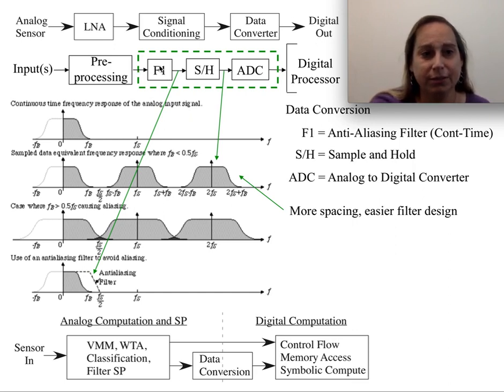And so usually that results in some sort of filtering stage. Then we do a sample and hold, which samples things, and then there's usually an ADC in the block. Typically when we talk about a data converter, you usually put the sample and hold in the data converter. There may in fact be some of the pre-filtering as part of it as well. And you might ask, well, why would I do this?